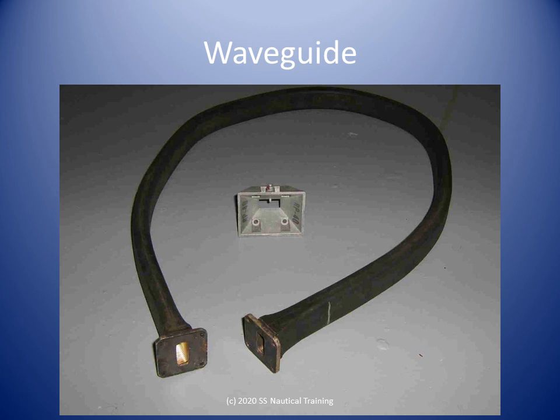The number of pulses sent out through the scanner per second is called the pulse repetition frequency. The pulses travel through the atmosphere at the speed of light and get reflected back after striking any target on their way. The reflected echoes reach back the scanner and the receiver processes and amplifies it and shows it on the display screen as a blip, which is identified as the detected target.